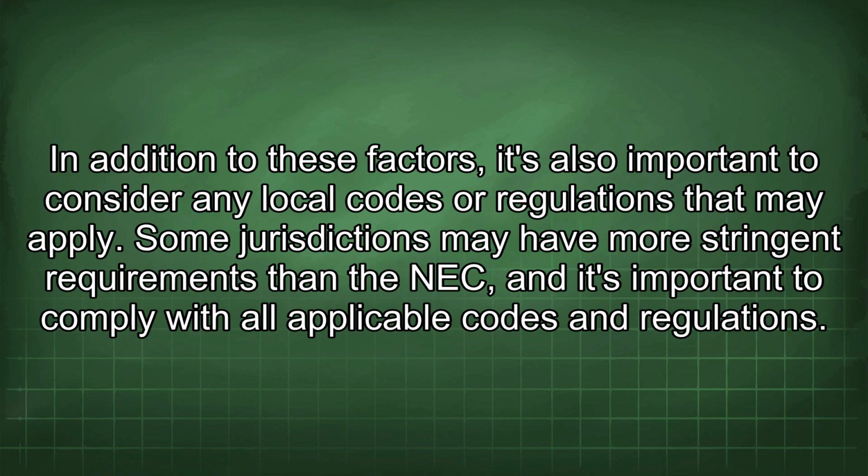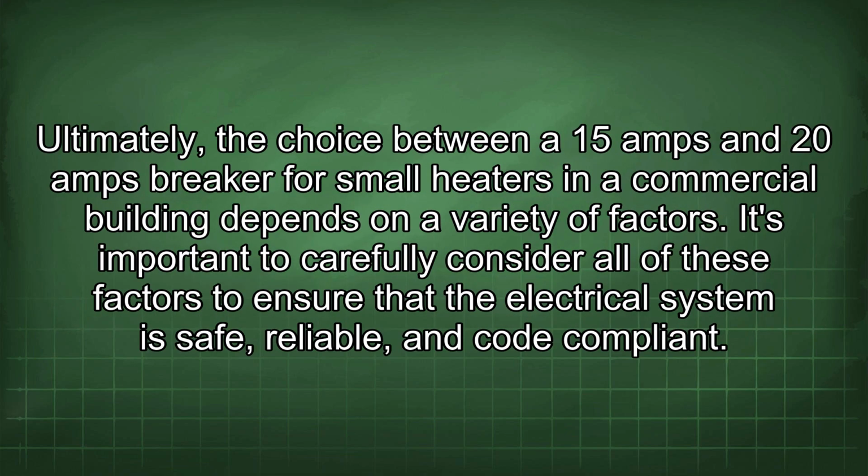In addition to these factors, it's also important to consider any local codes or regulations that may apply. Some jurisdictions may have more stringent requirements than the NEC, and it's important to comply with all applicable codes and regulations. Ultimately, the choice between a 15 amp and 20 amp breaker for small heaters in a commercial building depends on a variety of factors.